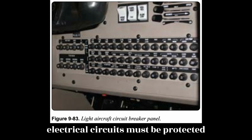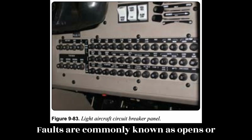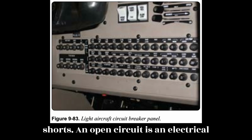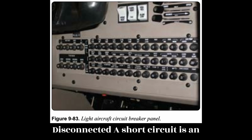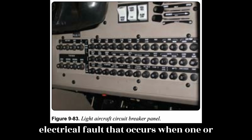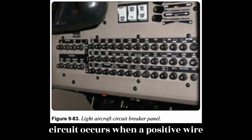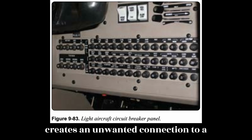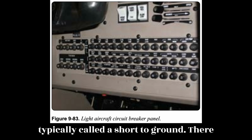Almost all electrical circuits must be protected from faults that can occur in the system. Faults are commonly known as opens or shorts. An open circuit is an electrical fault that occurs when a circuit becomes disconnected. A short circuit is an electrical fault that occurs when one or more circuits create an unwanted connection. The most dangerous short circuit occurs when a positive wire creates an unwanted connection to a negative connection or ground. This is typically called a short to ground.